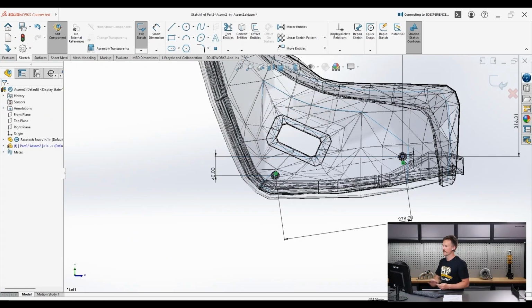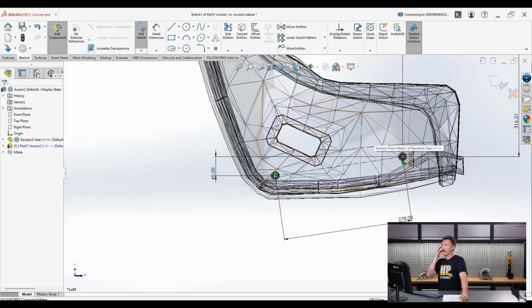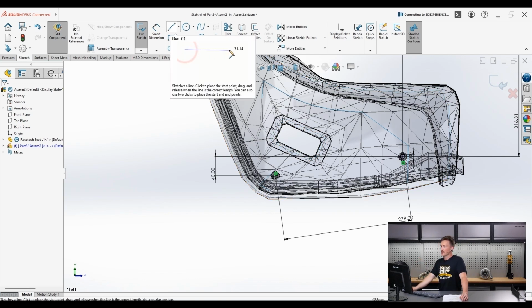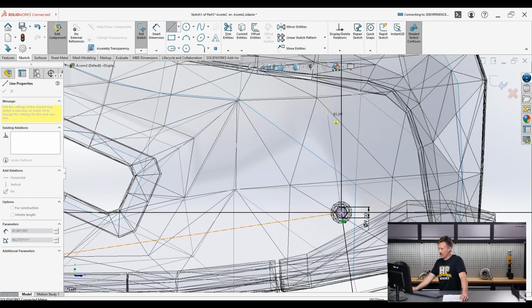So moving on from that, we're going to start creating the other array of holes. We're going to do 5 holes, just like some of the other photos we had there, for the front and rear, to give, I guess, 25 different positions that the seat could be tilted or installed in, without even moving it back and forward. So we'll start off here just by creating another line which is going to snap automatically to perpendicular with that line we just drew between the holes.